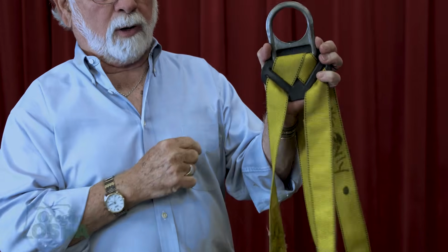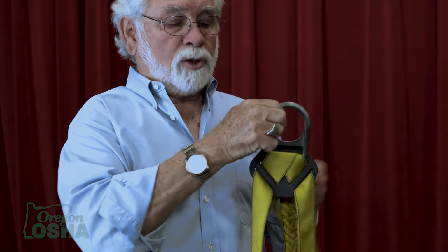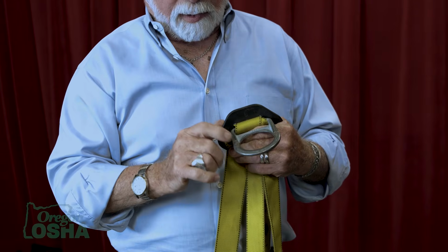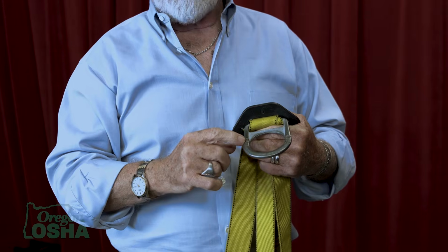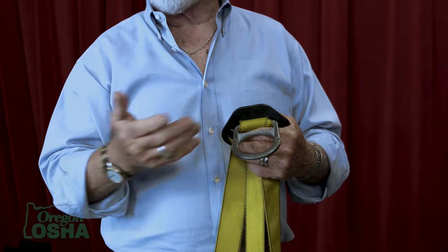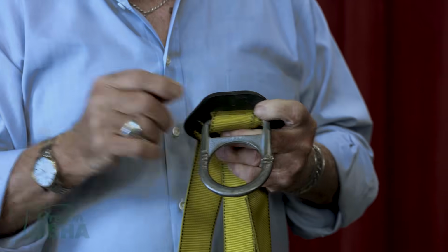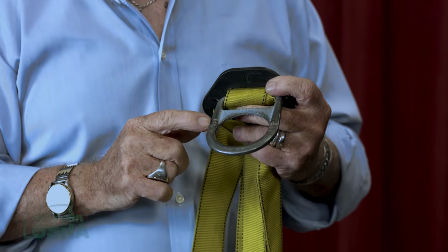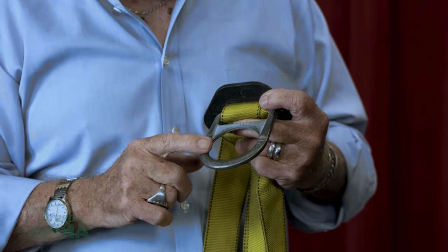We want to look at the D-ring, make sure it's round, feel it to make sure there's no nicks in it, check it to make sure there's no worn spots here. This is an actual reproduction of a harness that came out of the initial wind towers in Oregon, because when those towers are formed, the weldment to the inside had little sharp protrusions. And the fellows that were working in there would lean back on the tower and it would puncture their bodies and they would bleed. That's an accident.